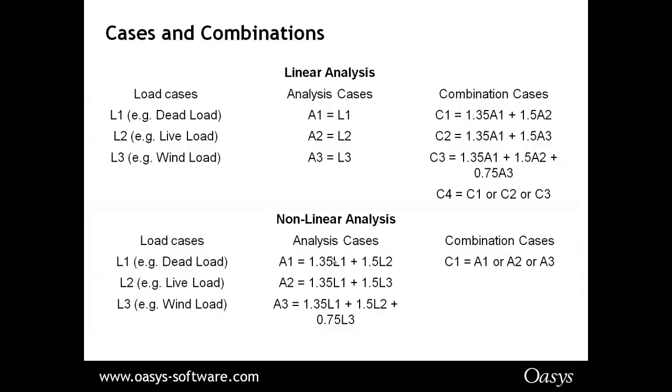Instead, within each analysis case, you then have to multiply and add the load cases together for the particular analysis task. Remember, because the loads are dependent on the final geometry and the load paths can change and so on, this is quite important. And the combination cases, the only combination case you're allowed is an envelope case.